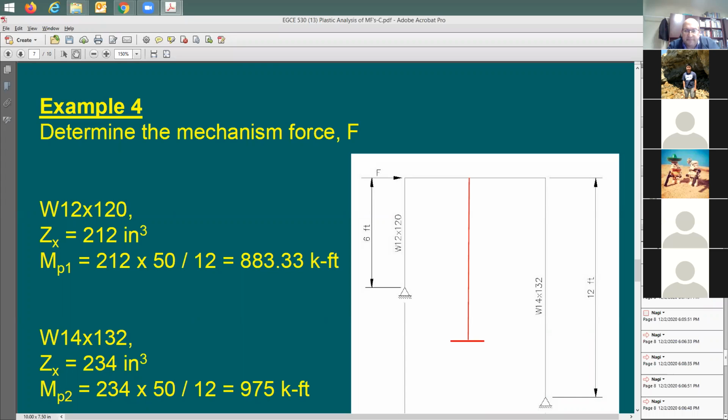Professor, in the submittal, what is the type of connection we have between the beams and the columns, and what are the columns' final support? Are they fixed? Which support are you talking about, the moment frame or the typical standard beam to column connection, or beam to beam, in the submittal course project? Which submittal? The upcoming one? Yes, sir, for this coming one. Okay. For this coming one, I'm not going to ask you to do the connection, but generally speaking, the connection in the moment frame has to be a fixed connection, like a moment connection. All right? It has to be fixed connection.